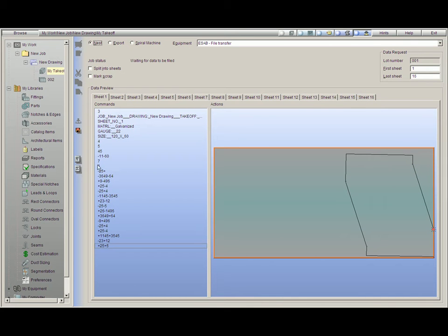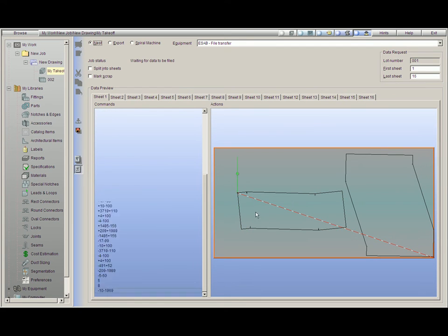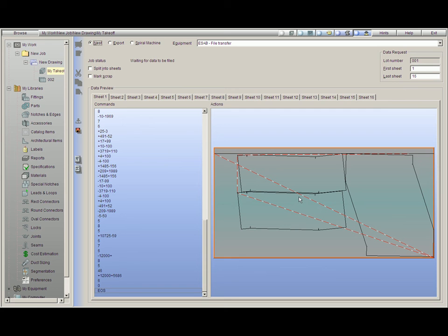If you'd like just to set it on automated and just hit trace the selected sheet and watch the whole sheet cut, just press the trace the selected sheet button once, and now you're going to see PractiCAM cut each piece. You can watch the entire cut path from start to finish. The red lines here of course are the free travel and when your cutter is not cutting. That'll conclude our section on fabrication.